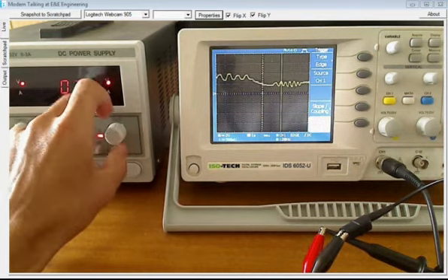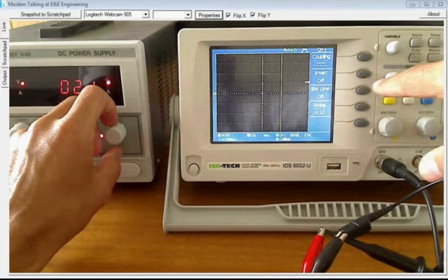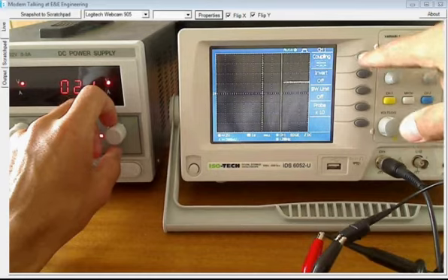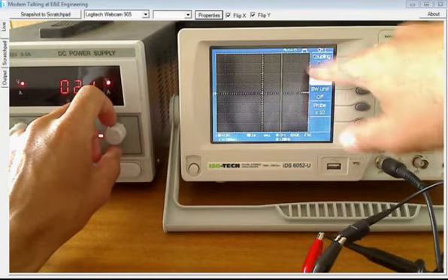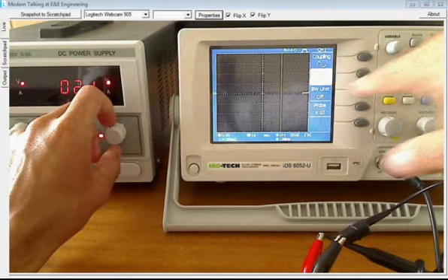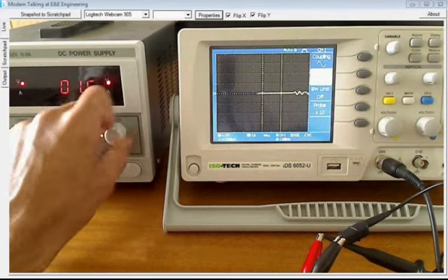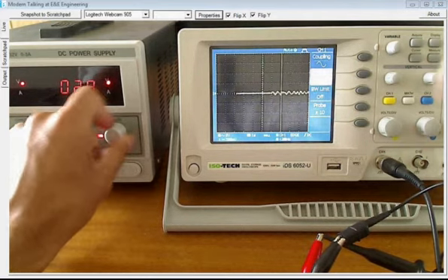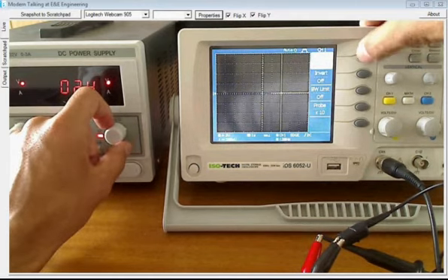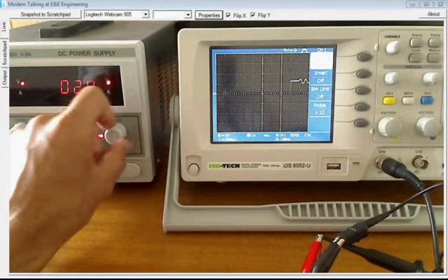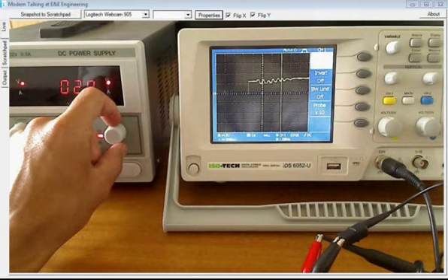By the way, just to demonstrate the purpose of that DC coupling, if I press channel 1 here and select coupling, I can make that AC. I don't know if you can see that, but it's essentially now a wave. That means it's AC coupled. So that DC voltage that I have there doesn't even show. If I do this, there we go. If I select DC couple, that's ground. Ground just says you're connected to ground. If I couple onto AC, you can see that DC voltage is back. So that's the purpose of that coupling thing, and many people get that wrong.